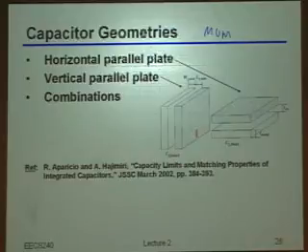To really understand that, let's start thinking about exactly what the trade-offs between these two are. So let's say I'm thinking about this horizontal parallel plate here. What is it that you can control, and what is it that's basically fixed by the foundry? Yeah, the dielectric thickness here, the dielectric material, is totally fixed by the foundry, right? But what is it that you can actually control? Yeah, you can change the width and the length of these structures, so you can make these arbitrarily big, right?